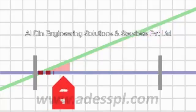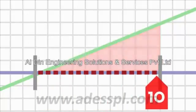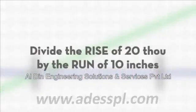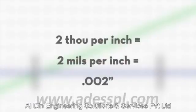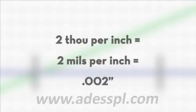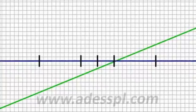In geometry, this concept is called slope, or rise over run. Angularity or slope expresses the amount of rise or fall of the movable shaft over each unit of measurement along the shaft's length. Angularity is expressed as thousandths per inch.